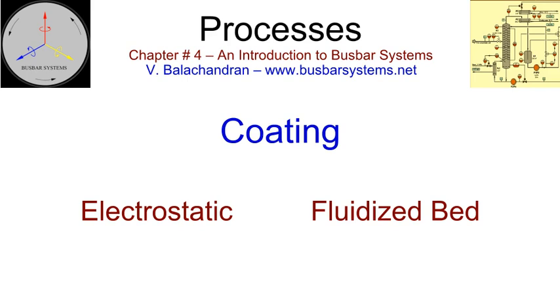The coated conductors share the voltage stress under normal operating conditions. The ratio of the burden can be evaluated based on an equivalent circuit of two capacitances in series. In this design, the coated conductor has to undergo a routine power frequency voltage withstand test before it is assembled on the insulator inside a bus duct.